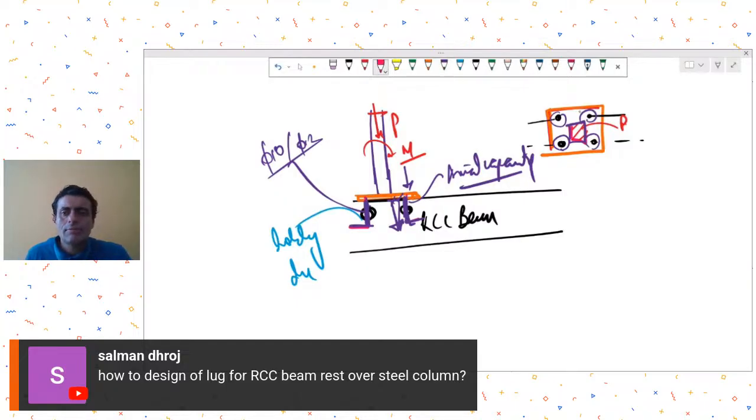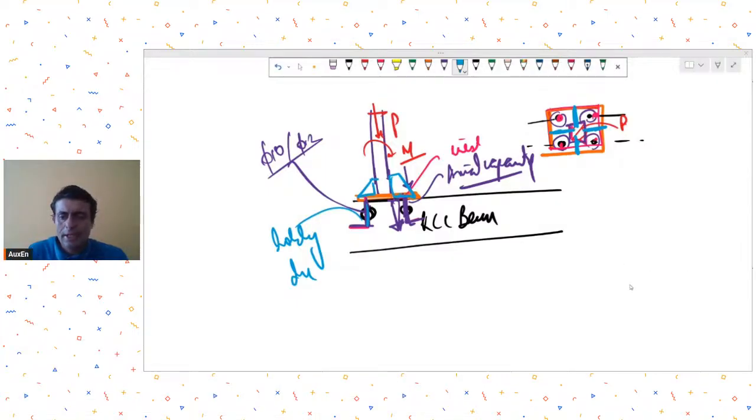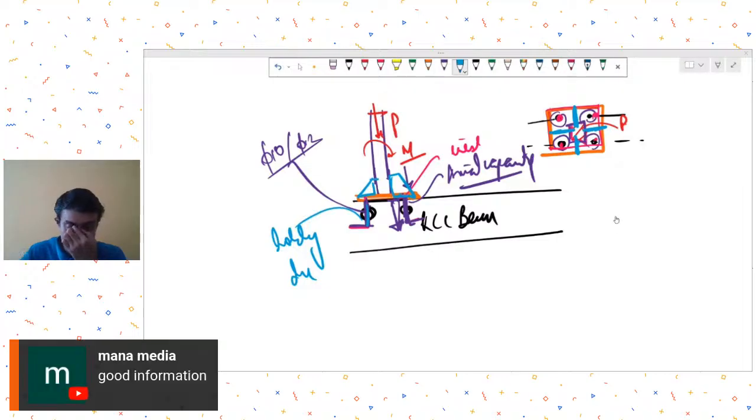And then for this insert plate, so this is called the insert plate, you design your insert plate in the same manner you would have designed if you had these 4 bolts, let's say. If you want to reduce the thickness, it is better to add stiffeners and all those things to your column. So that process remains the same. For lugs, my sense would be to design it as you do for bolts. The reaction calculation and those shall be done as you do for your normal bolts.